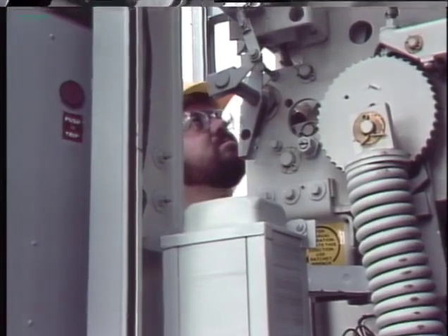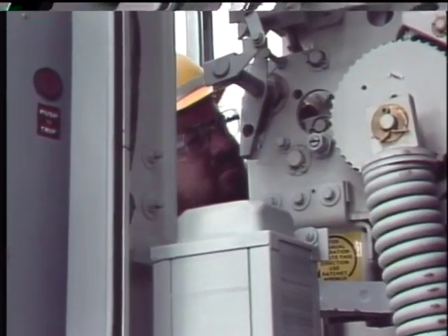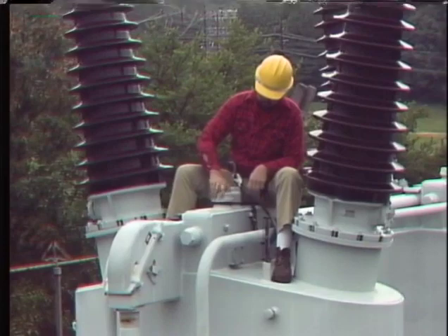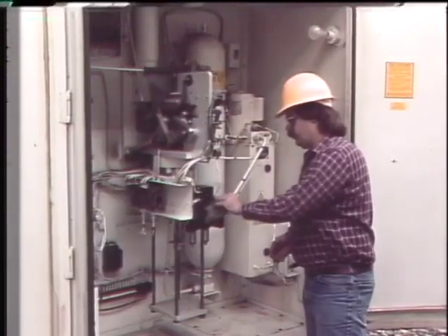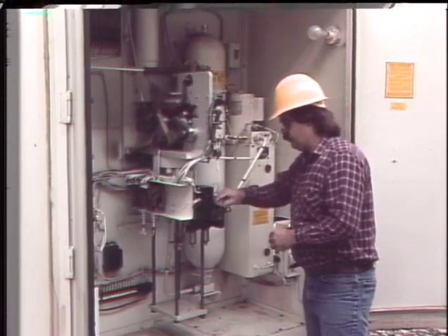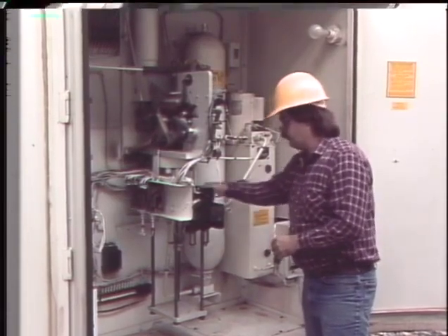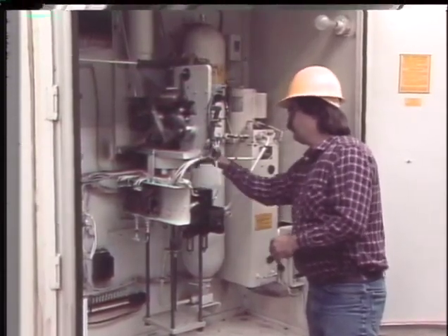General maintenance for breaker operating mechanisms is similar to general maintenance for the breaker itself. The tasks include inspecting for damage, checking adjustments, and cleaning. A little bit of dirt might not seem like a big problem, but it can cause friction and wear that may slow the mechanism down or prevent it from working and can reduce its effective life.